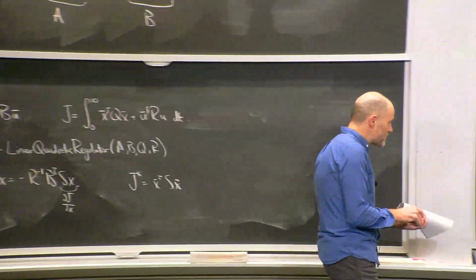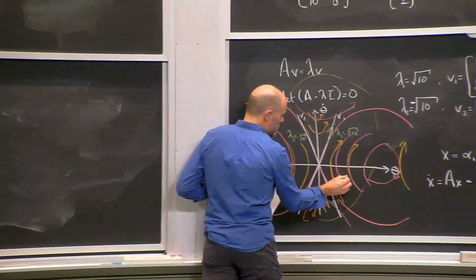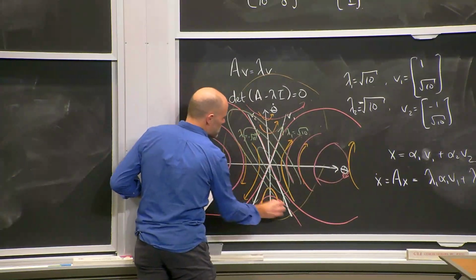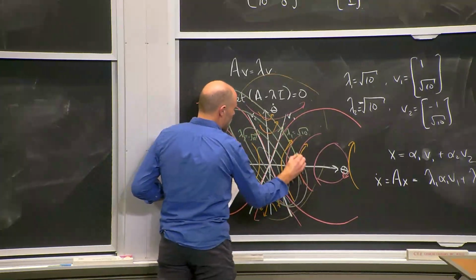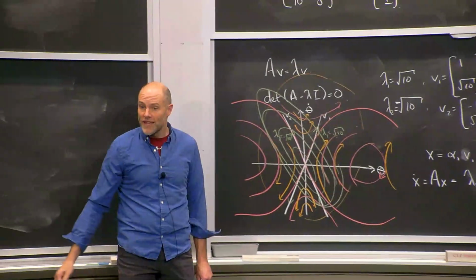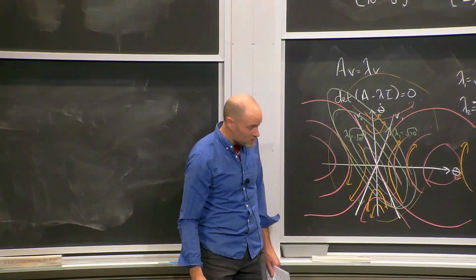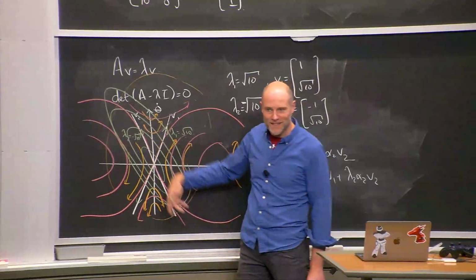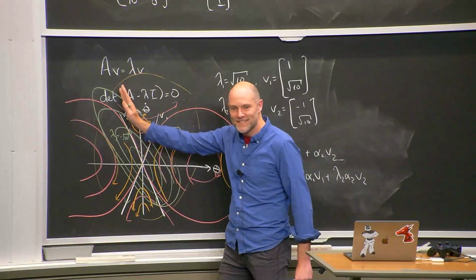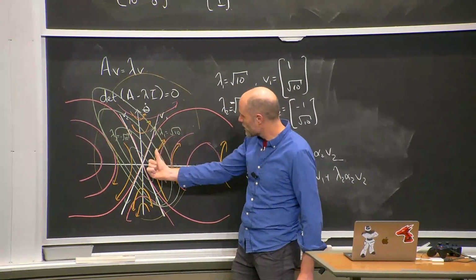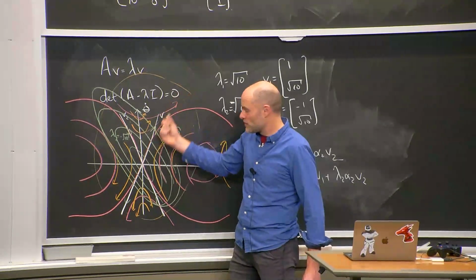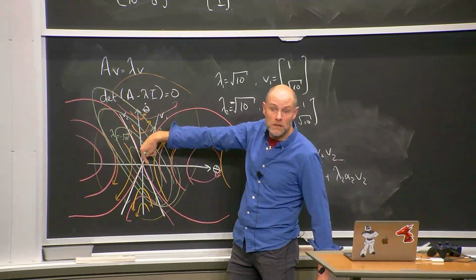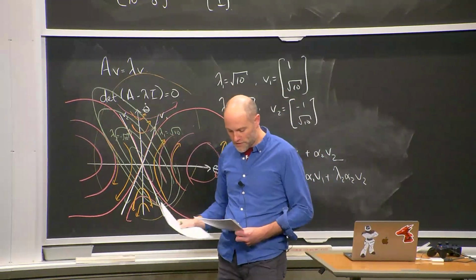And that S for the pendulum gives us a cost-to-go function that looks like this, that is elongated along the dynamics of the pendulum. That was supposed to be symmetric around this point. It's a little bit bad artwork there, but the important point is that it's elongated this way. The cost of being along this vector, which is pushing you away, goes up faster than if you're along this vector, which is already bringing you back towards the origin. And LQR discovers that beautifully.